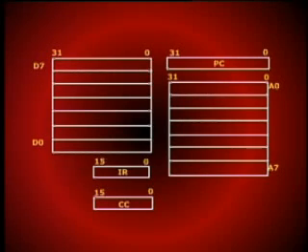The second set is the address registers from A0 to A7, also of 32 bits. PC is the program counter having 32 bits, but only the lower 24 bits are used for addressing the memory. IR is a 16-bit register, and CC is the condition code or the processor status register.